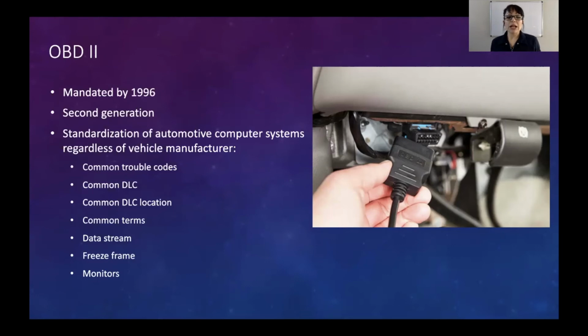Now what's cool is next is freeze frame. Freeze frame is where, if you have a problem with the engine, the PCM sees a couple of sensor signals that it does not like. Let's say it's got a misfire, right? And the PCM says, okay, we've got this. If it sees cylinder number 4 misfire, it's going to be like, ooh, I've got my eye on you.